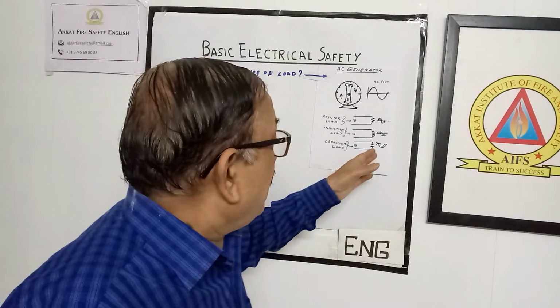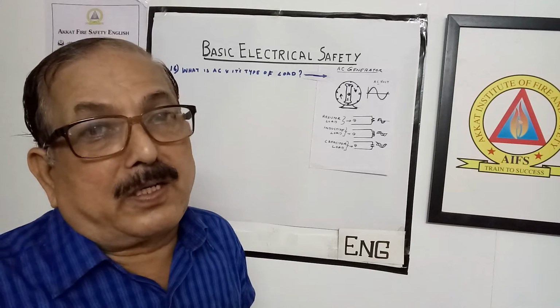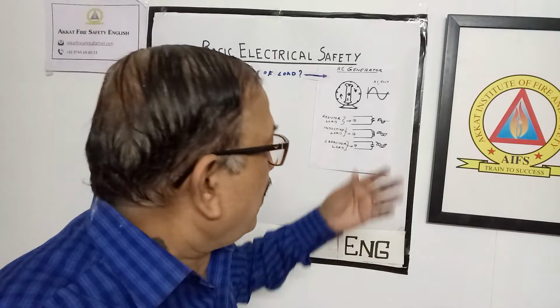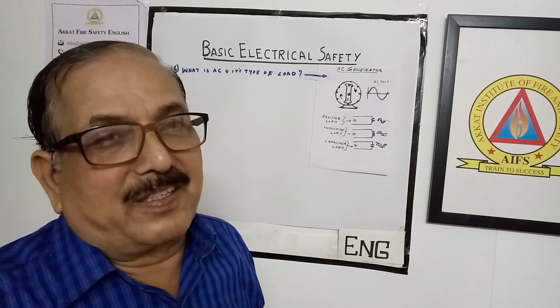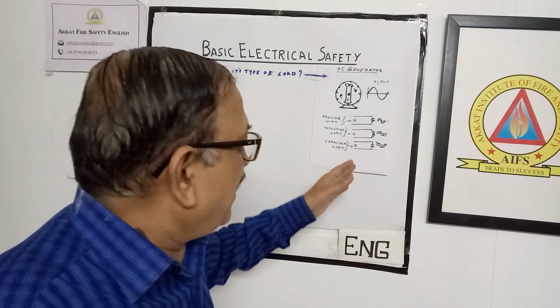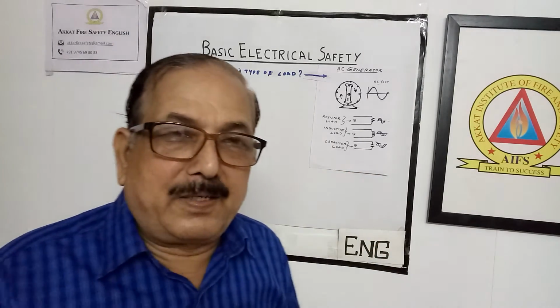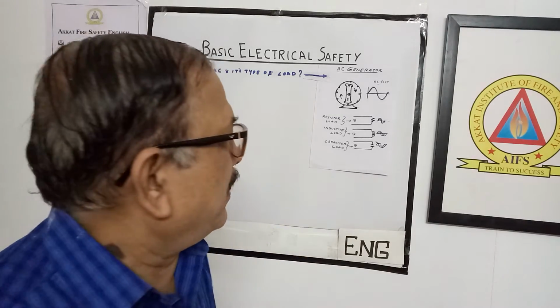So here it is just the opposite of the inductance. In inductance, first voltage appears, and then after 90 degree the current will be coming. Here first current started coming, then only the voltage is appearing. That means 90 degree leading in a capacitor. Here also practically it is not possible at all for a complete capacitor; some resistive part will also be there.